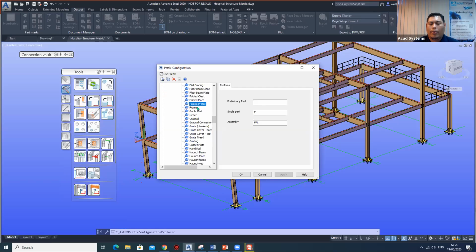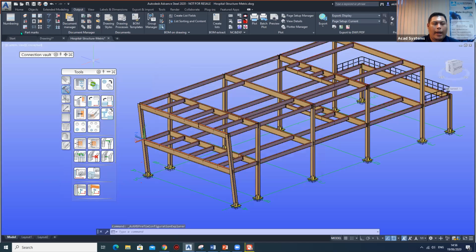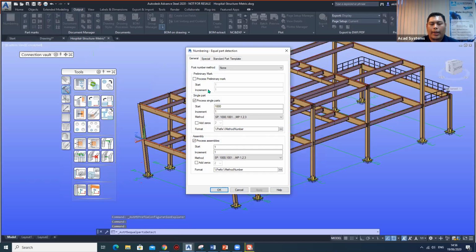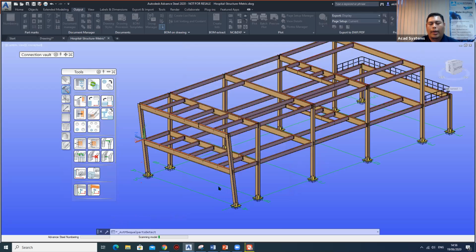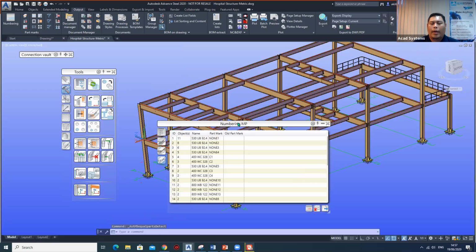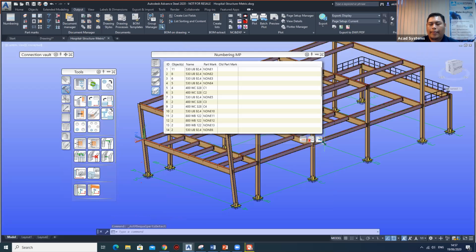This is for instance, and there are a few things that you may forget to key in, which is okay. I will show you the difference between those we key in or not. Then we can also generate the numbering once we're done. We can generate the process number, assembly numbering, and also part numbering. We can set the increment if you want different increment settings like this. Then we just click OK, and the software will help you to calculate the numbering and generate things like this.